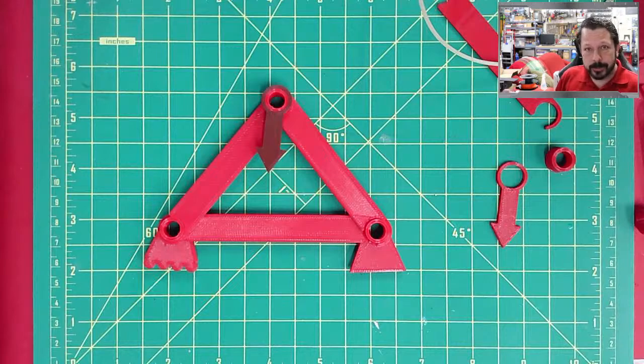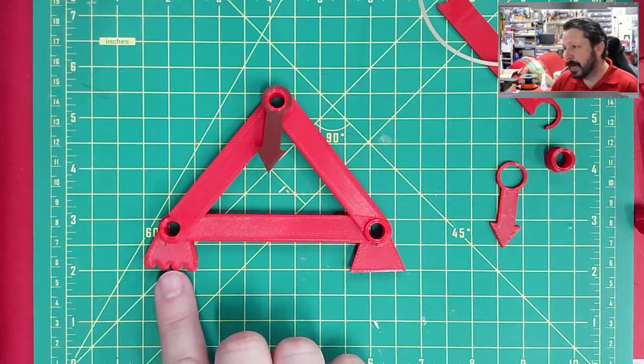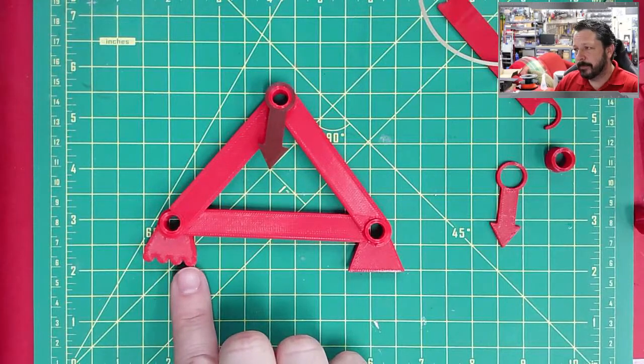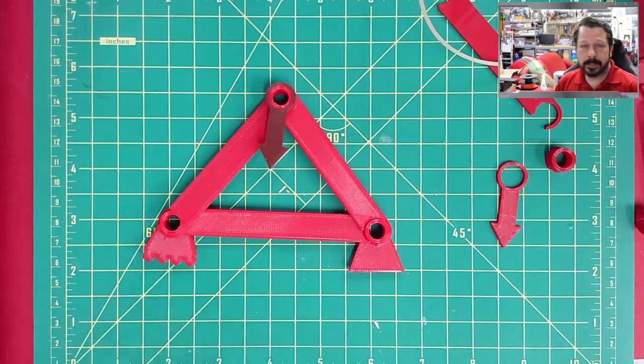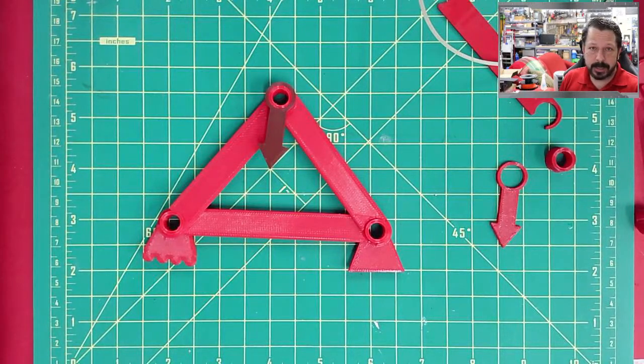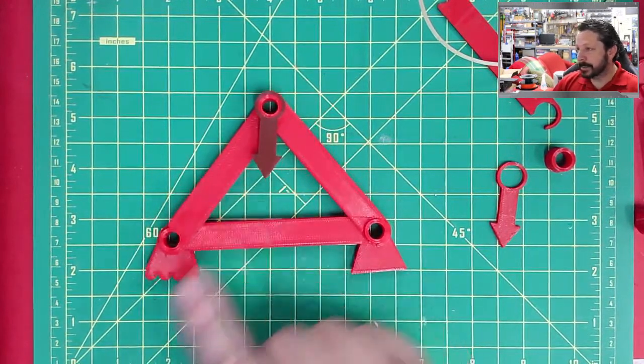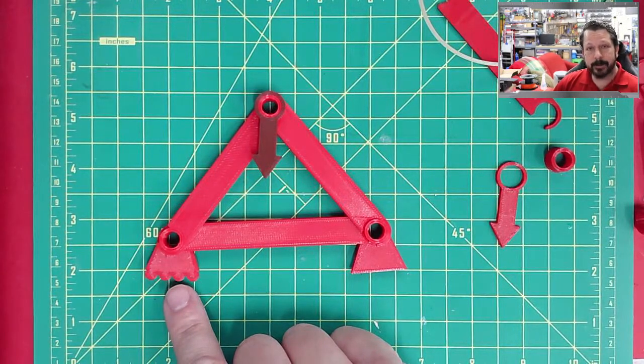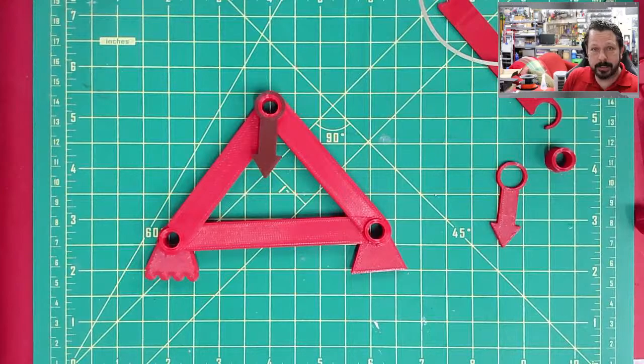Or it gets cold and it wants to shrink and it can't. So you really do have these types of fixtures in trusses just so that there's some allowance for changes in size due to temperature changes. If you ever drive across a bridge and you hear that periodic thumping sound, it's because there are expansion joints in the bridge that are doing this exact thing. They're not necessarily rollers with wheels, but they're a way for that piece of the bridge to change its length a little bit, without having to crash into the next piece of bridge and buckle or tear it apart.